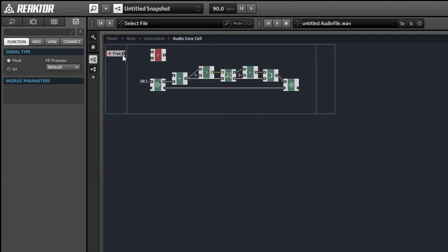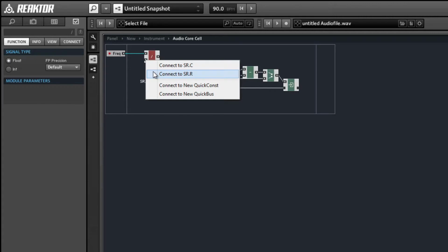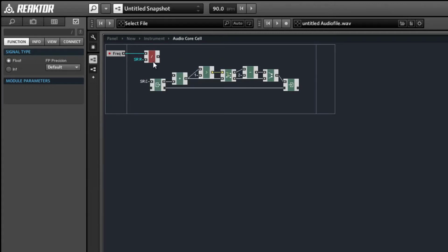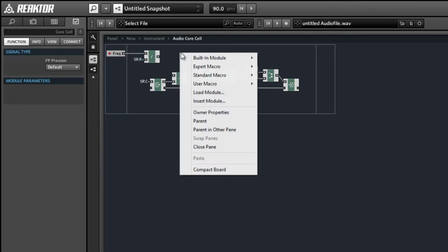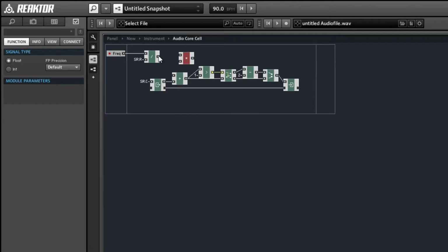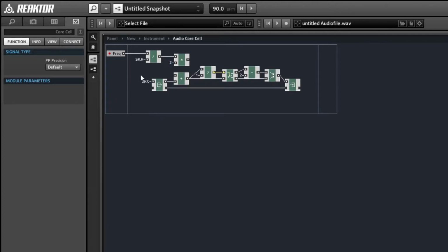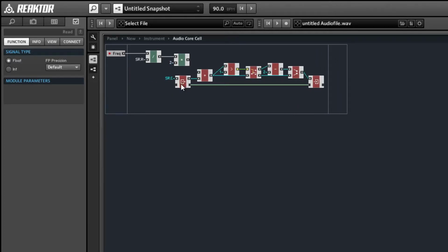And we're going to take the output of that value and multiply it by 2. What this gives us is a number that, when we add it together 44,100 times per second, as we will end up doing with my sample rate set to that value, will add up to twice the frequency of our oscillator. The reason we want it to add up to twice the frequency is we are keeping our phase accumulator in a range from -1 to 1, so it's got a range of 2.